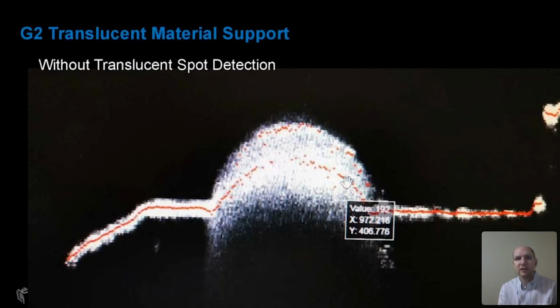And this is simply because in the previous spot detection methods that we have given you, easily accessible through the UI, it would find the highest point in the fit Gaussian for each of these columns. So it would be performing a center of gravity based approach and finding the spot, but really using all the data within this region here. So this is the glue bead applied on top of a surface, and this is an example of how it would fail because it's not really finding the top surface of the glue that you want to inspect. Everything else here is fine, but in this glue region, it's not doing well.